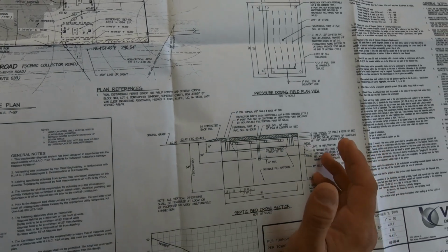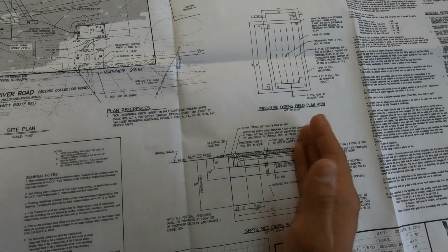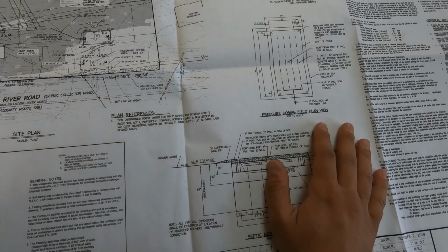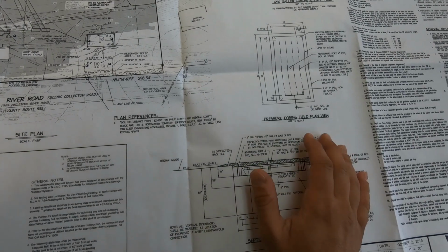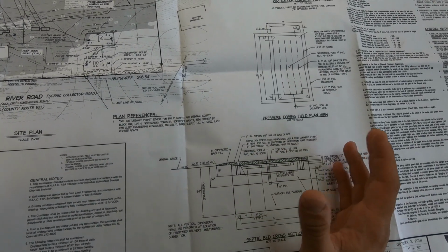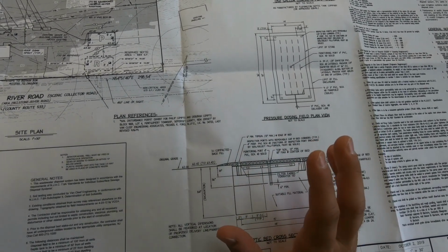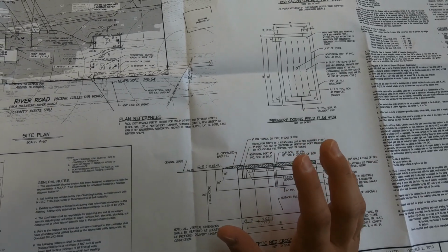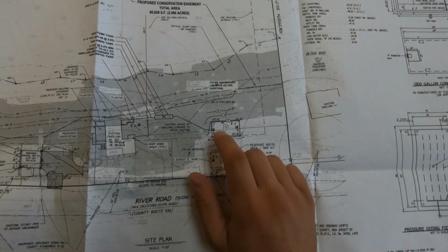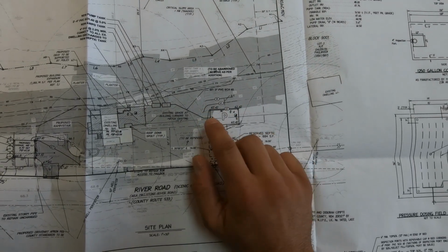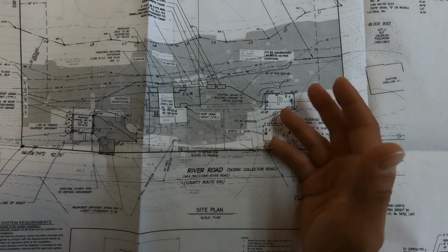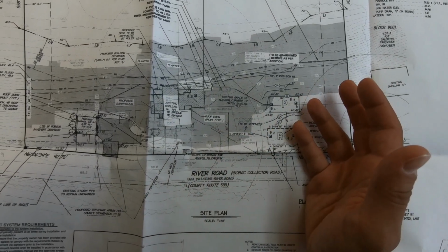So the as-built can be done a couple of different ways. Sometimes we have the survey crew go out, especially if it's like a new construction, like a totally new dwelling and everything. Sometimes if it's an existing dwelling, or if it's just an alteration to the septic system, we'll take tape measures. So you'll take a tape measure from each of the 4 corner inspection ports, and you're trying to tie that to some permanent feature of the property.